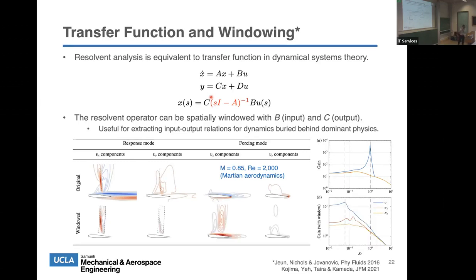However, if you window it the right way, so if you window it right here and ask, when can the shock oscillate? It turns out you can actually get the responsible modes to induce buffeting. Buffeting won't induce at these conditions usually, but if you perturb it the wrong way, it can. That's what this study is showing. So we're pretty excited to see this. And in fact, what we did was we put in this exact perturbation into the flow and started to see buffeting. Okay, so this was kind of a warning to us that although we don't see it at this particular condition, if the structure starts to vibrate at the wrong place, we might be able to see buffeting, which would be kind of bad for those little flying objects.